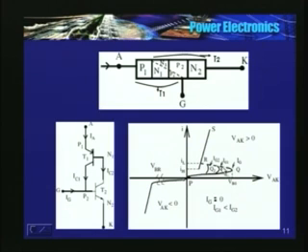Why did I show this to be dotted? Why is it not firm, like P to Q? This is because this region is an unstable region. Why is it unstable? Because it is a negative resistance region. See, voltage is falling, current is increasing. The slope of this line is negative resistance region, so it is unstable.